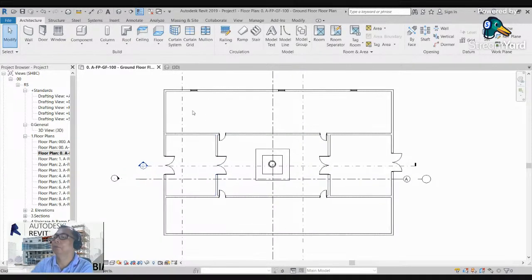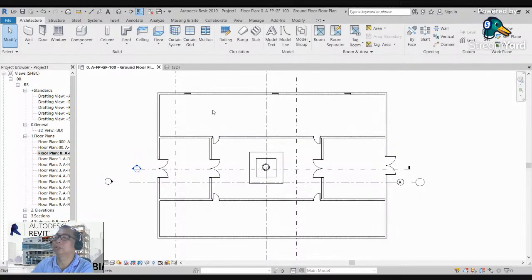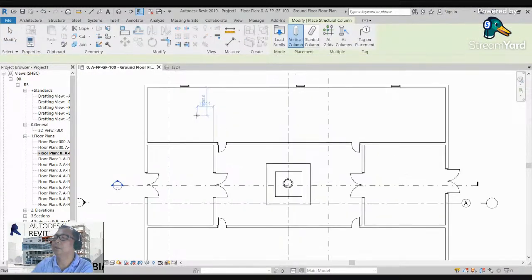And then column for the architectural, this is only for the facades, no, we are using this for the facades because this will not be a solid concrete. The structural column is a solid concrete, so that's why when you put the discipline, if you place that discipline on structural, it will remove the architectural column. To avoid that, it's better to use the structural column.